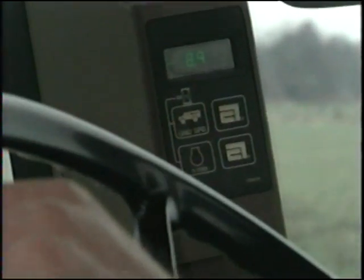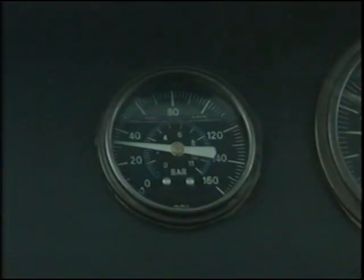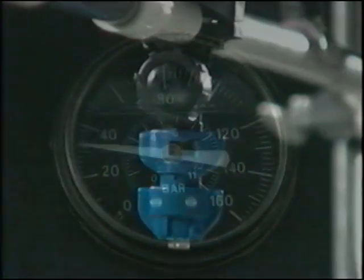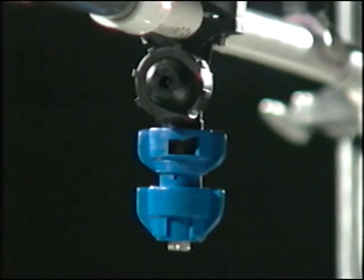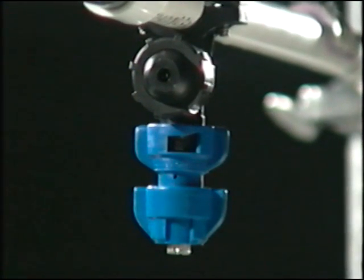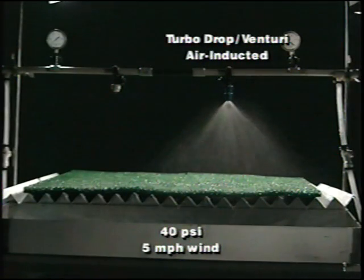When an applicator is subject to operating at a variety of sprayer speeds, he needs a nozzle design that is less sensitive to pressure variance. The Turbo Drop Venturi air-inducted nozzle allows reduced drift performance at higher spray pressures. Here, we see this new nozzle spraying at 40 psi pressure in a 5-mile-per-hour wind.